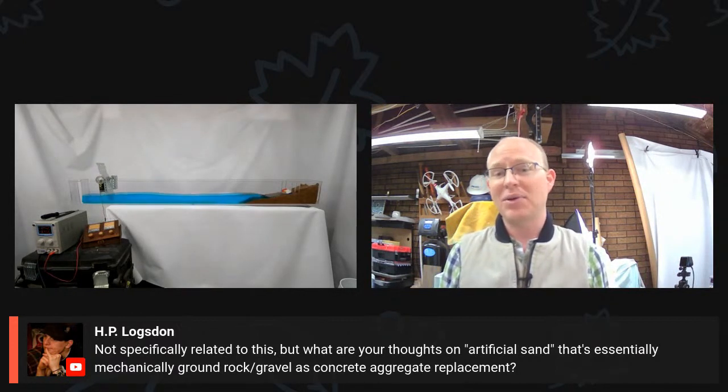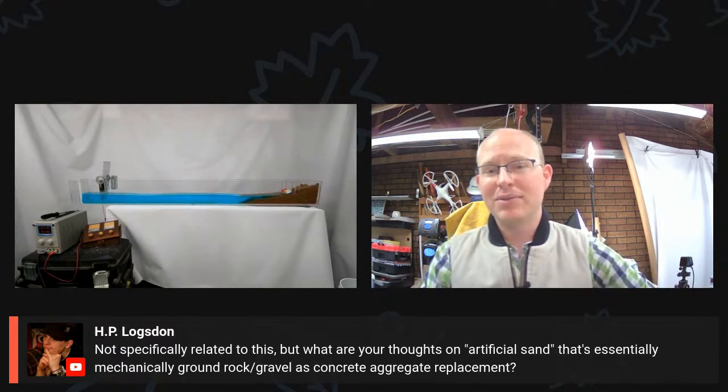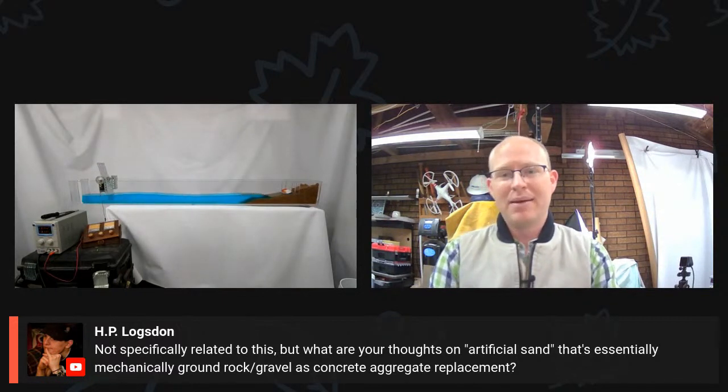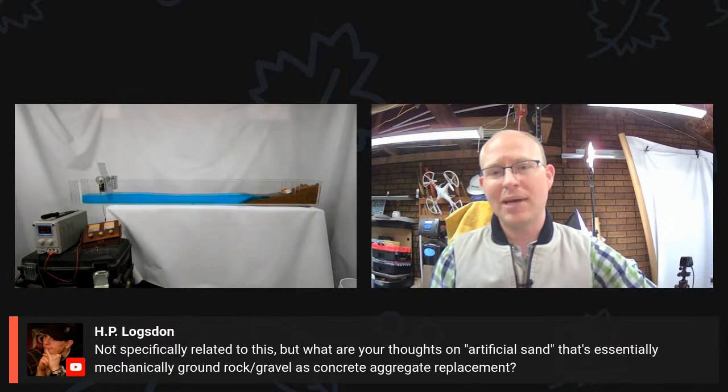And in that case, yeah, you're using quote unquote artificial sand to supplement or change the properties of the sand that you do have. So this is a really common thing. I'm sure in some way it adds to the cost of the concrete, but in general, this is something that concrete manufacturers and quarries do every day. So nothing unusual about that.